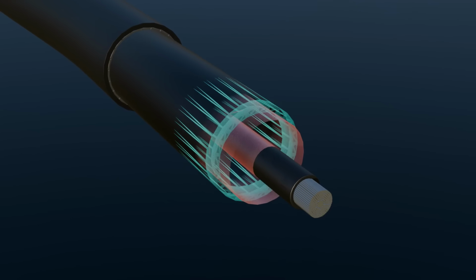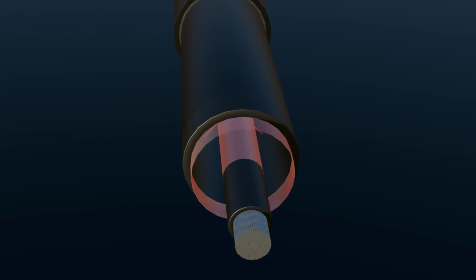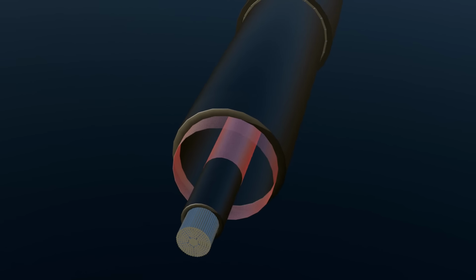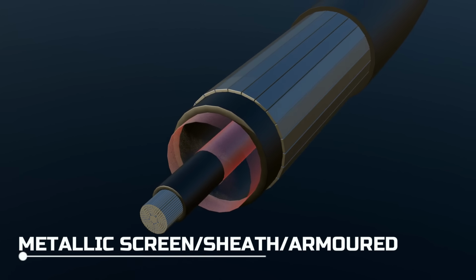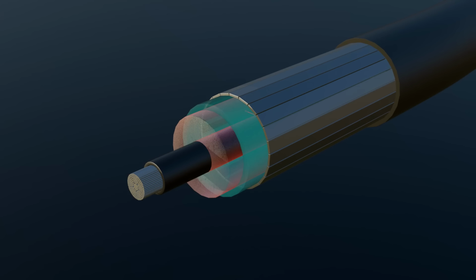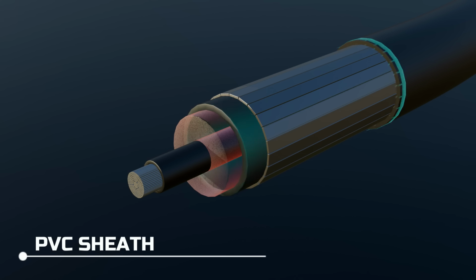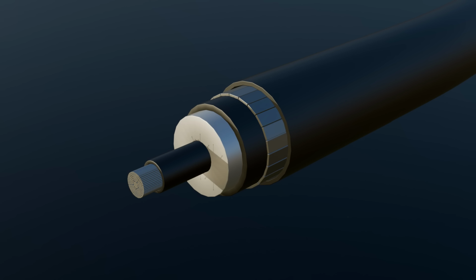For this, an insulation screen is applied, helping the electric field end in a controlled and smooth way. A metallic screen is applied around the insulation screen. Any voltage induced by the electric field is given a safe path to Earth through this metallic screen. It is also called a metallic sheath, and depending on the cable design, an armor layer may also be added outside it. Finally, a PVC protective sheath is applied on the outermost layer. It protects the cable from external physical damage and moisture.